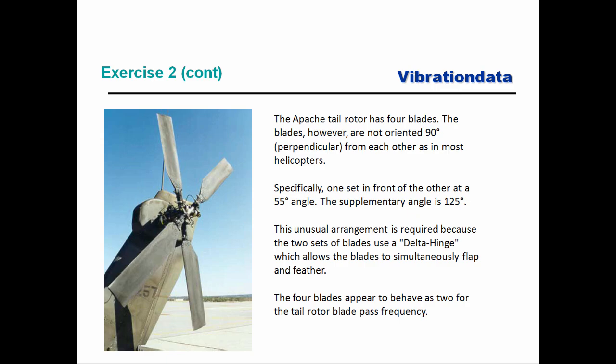So that has one sort of directivity pattern, but this vertically oriented tail rotor is going to have a directivity pattern that's going to yield a more direct and a stronger transmission path to the ground as well. So those are the 2 reasons why the tail rotor has the highest individual spectral frequency. And why did that happen at the times 3 multiple? I'm not sure. I'm sure there's some acoustic theory that could account for that.